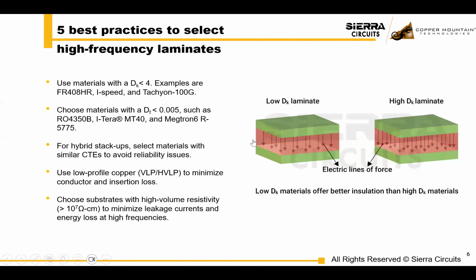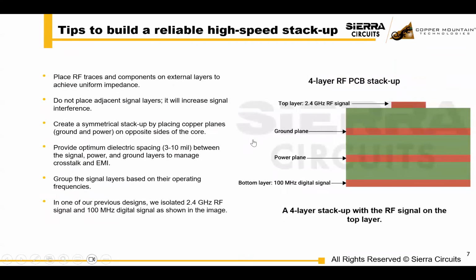Now, when you opt for a hybrid stack up, you can also introduce other manufacturing issues. Like when you are programming your drill machines, you want to make sure that you program it just right for the hybrid materials. When you program your plasma, you want to make sure you program it just right for the mixed materials. So although it will get you a less costly stack up, it could also introduce more complications in the manufacturing. So you have to talk to your manufacturer to make sure they can handle that type of construction.